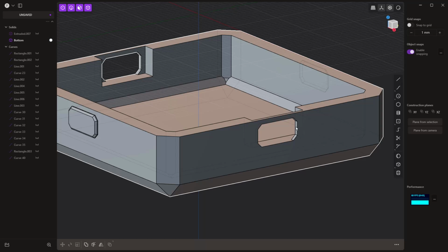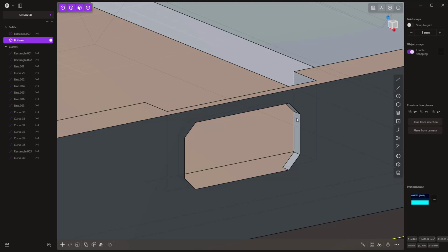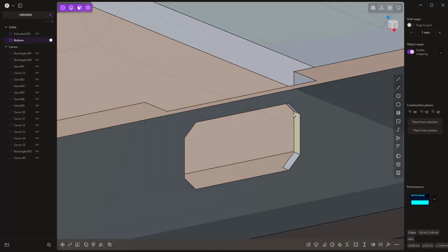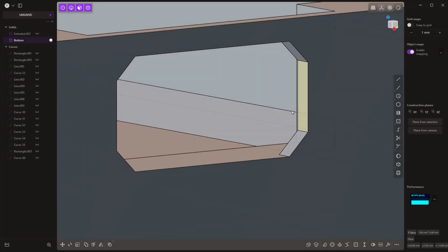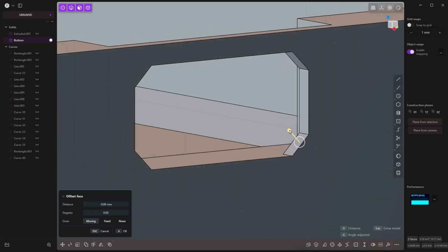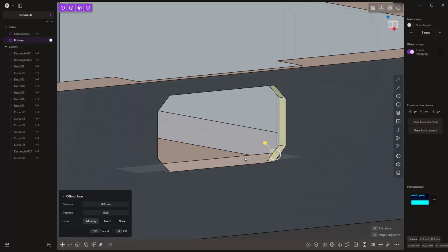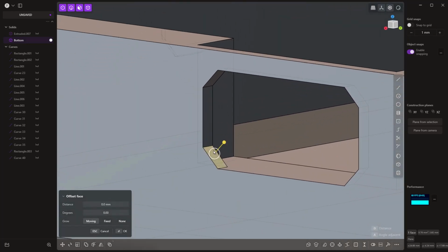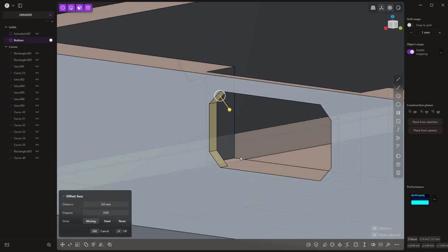And if we want to offset the sides, we can simply take these walls and begin offsetting them, but notice that it leaves those chamfers in place. So you want to make sure that you select enough faces to make this work. So Control and begin pulling these out a distance of minus 0.1. This is going to give us an overall gap of 0.2 millimeters, and the reason for that is because we're offsetting it on both sides. So we're going to go ahead and do this here. Again, minus 0.1. That's going to leave the top and bottom the exact size.